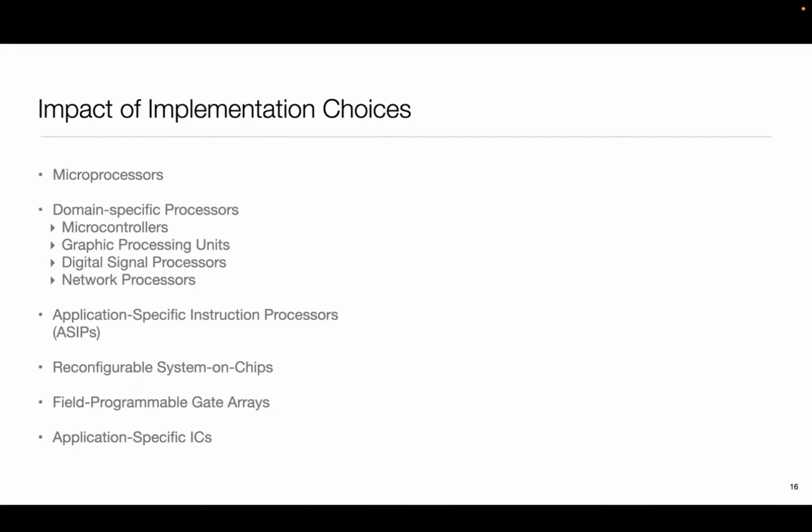The other thing also is when you are mapping it into FPGAs, you often are much more constrained because you have a fixed amount of hardware, and you also have to worry about things like power and more complicated compilation tasks. So there are people who work in an area called EDA, electronic design automation, which is like the counterpart of people in computer science who work on compilers. Other terms that you will see are silicon compilers, behavior compilers. So these are all compilers on the hardware side of things.